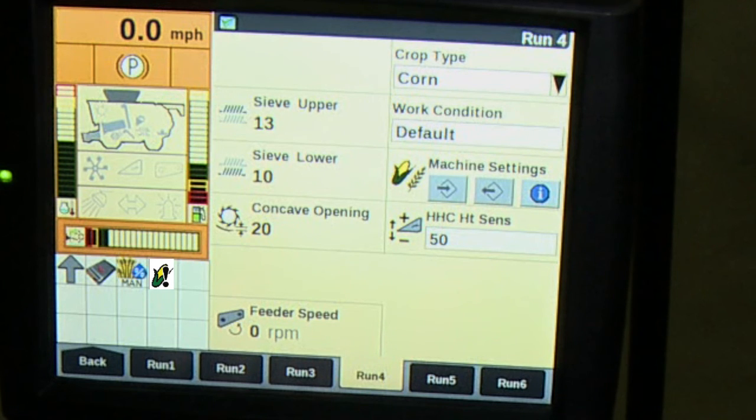As an example, if you were going into wheat and needed to get a higher RPM value than what first gear of that rotor gearbox would mechanically allow you to achieve, it would give you a cannot reach machine setting icon popping up in that lower left-hand status and warning icon area.